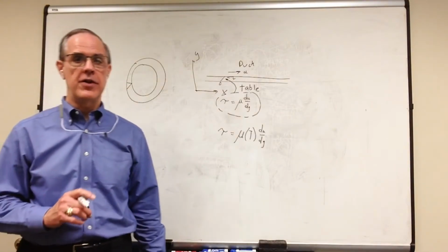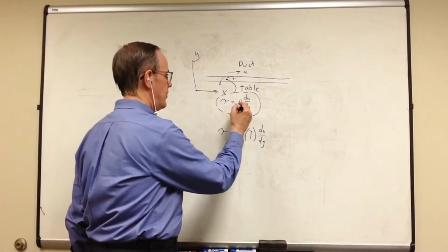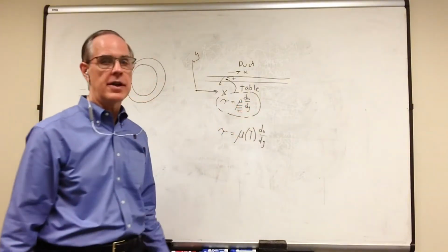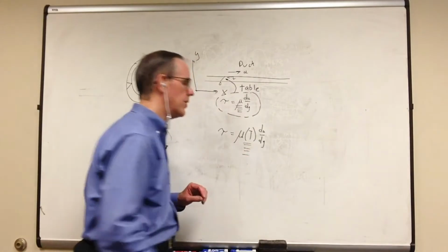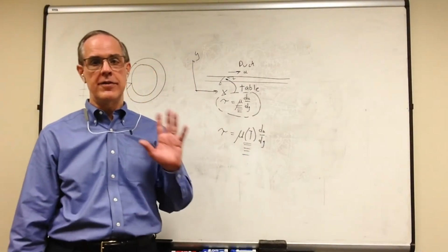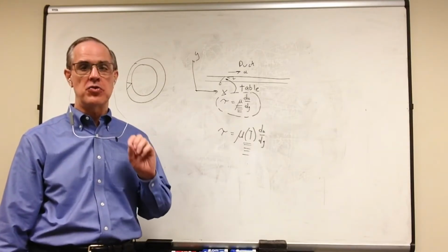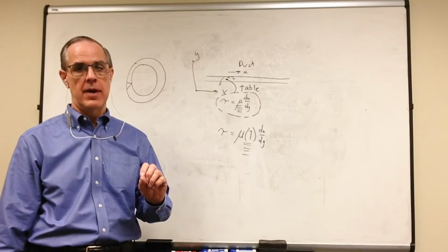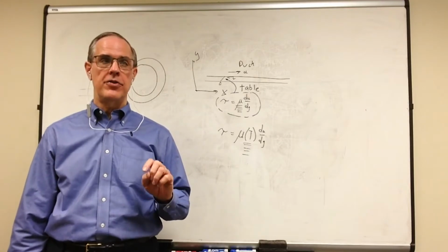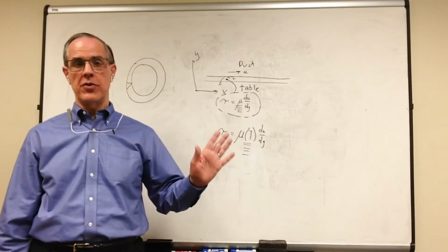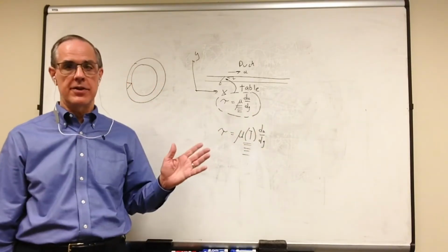Now, let's do a definition. I kind of blew past it in the beginning. This assumes that the viscosity for a given fluid is a constant, that the viscosity is only a function of temperature. If we hold the temperature constant, the viscosity will be constant. That is true if the fluid is Newtonian. If the fluid is Newtonian, then it is independent of shear rate. Shear rate fast, shear rate slow, it doesn't matter.